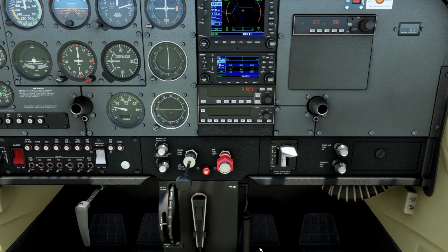One last thing I'll say about the autopilot before we get in the air and start playing around with the functions is that I recommend the first time that you engage the autopilot, you do it in level flight, and definitely not after takeoff. The reason I say this is because the default vertical mode when you engage the autopilot in Flight Simulator is a vertical speed hold of 0 feet per minute. So when you first turn it on, that's what it's going to do, and if you're climbing out on takeoff, that will stop your climb, and if you're down kind of low, that can get a little sporty. We will talk about a way to engage it while you're on the takeoff climb out. You do have to be a little quick in getting it into a decent vertical speed mode, but we will talk about how to do that after we go through the basic engagement functions.